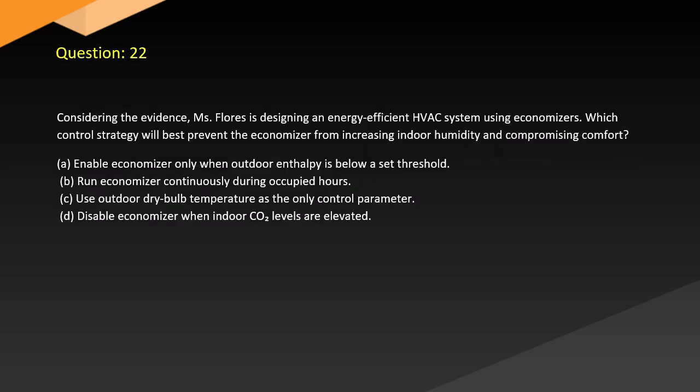Question 22. Considering the evidence, Flores is designing an energy-efficient HVAC system using economizers. Which control strategy will best prevent the economizer from increasing indoor humidity and compromising comfort? A. Enable economizer only when outdoor enthalpy is below a set threshold.